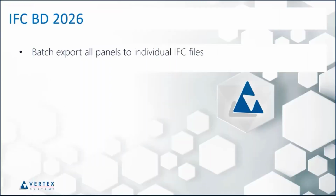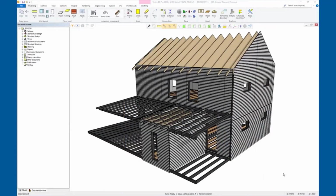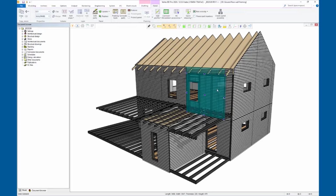Let's take a look at batch exporting all panels to individual IFC files. We have had requests for the ability to export separate panels when you have large buildings or structures. Of course, you can do it by selecting the panel, hiding others, and choosing to export only visible, but now it's possible to batch export these.